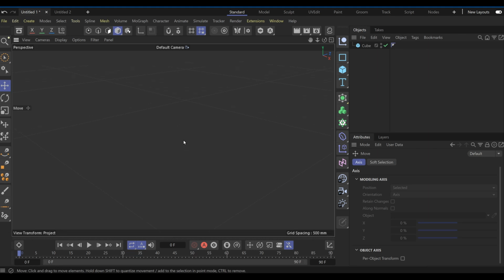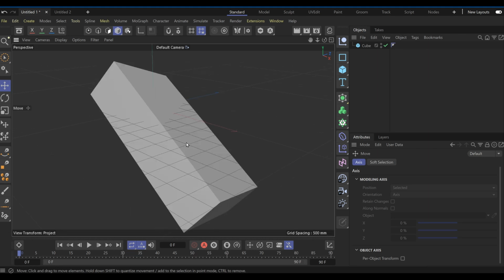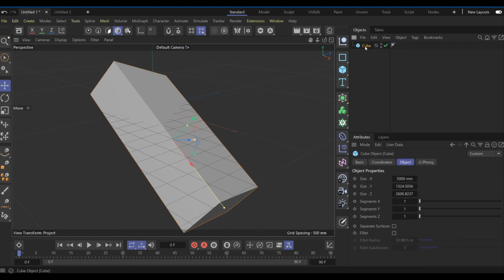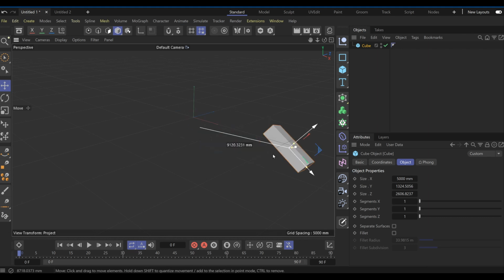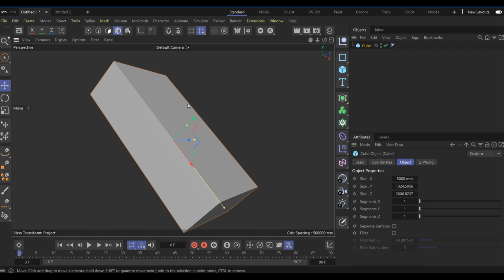What you can do specifically is if you press H, it will frame all of the objects in the scene. In this case, we only have the one object, but it'll frame it. If you've selected an object, let's say you have a few of them, you can press O. Let's move that object over there, and I'm going to press O, and it'll select it again. So H and O allow you to get back to right where you want in either the scene or the object itself.